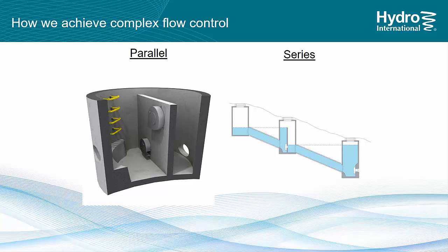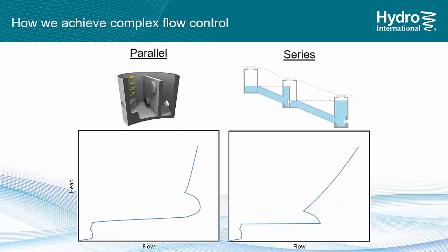Sometimes it can be more appropriate for certain sites to start having them in series, especially if you have large increases in the amount of flow that is going to come through the system, say from your 1 in 1 year to your 1 in 100 year. This is where we end up drowning out the smaller first flow control with a larger flow control.